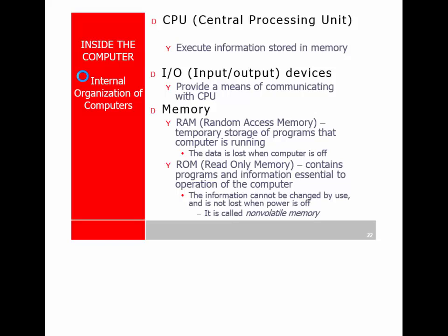We've got 2 types of memory that we're going to be dealing with. One is ROM. The term ROM is somewhat fuzzy today. These terms change. I'm using slides from an older book, which the books we're using are a little bit older. The term ROM basically means read-only memory. You can't write to it. It's non-volatile. You turn the computer off, it's still there the next time you turn it on. But most of the ROMs today are reprogrammable.